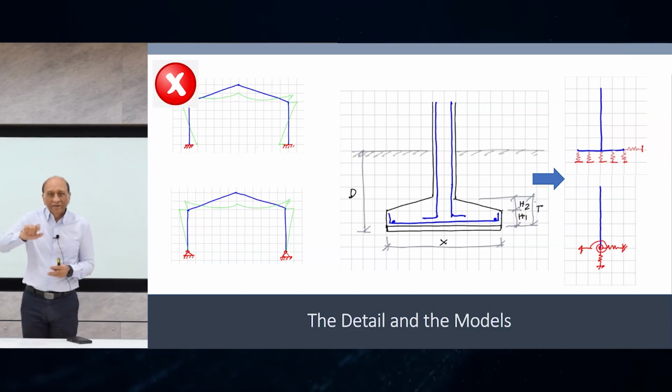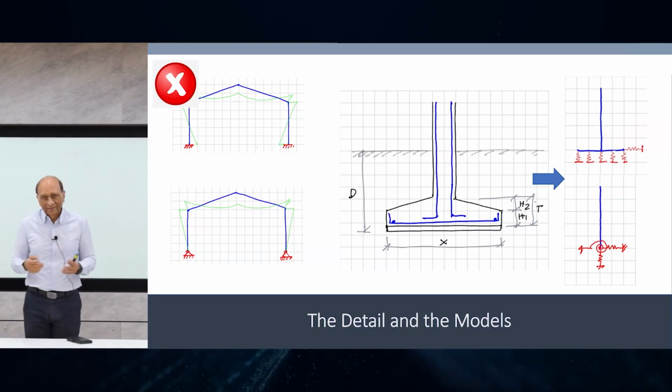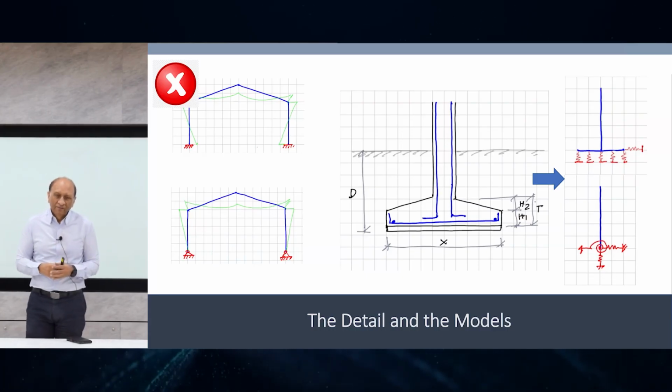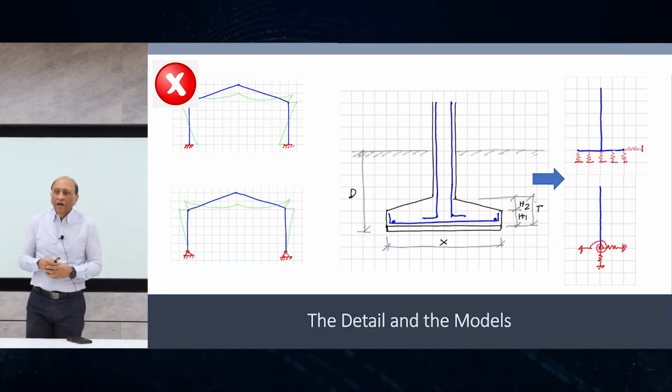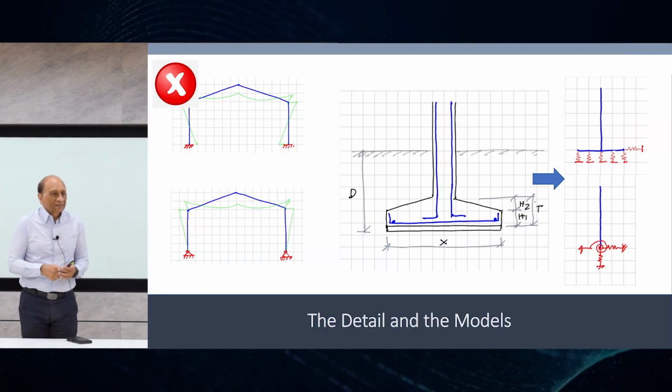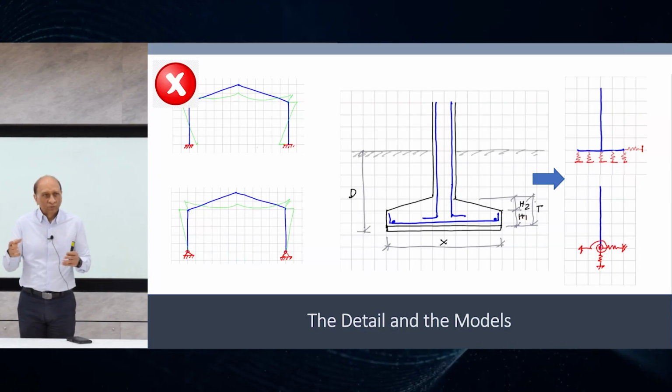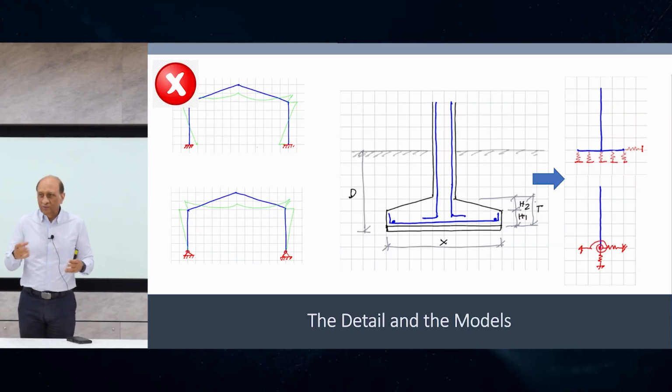This three spring concept was the one that at that time I thought, oh, this is great. But the problem is calculating the rotational spring is not easy, right? And then putting them in, I had no software at that time. Actually, I was developing my first frame analysis program. So I thought, if I develop the program myself, how can I incorporate this there? I couldn't implement a spring element.